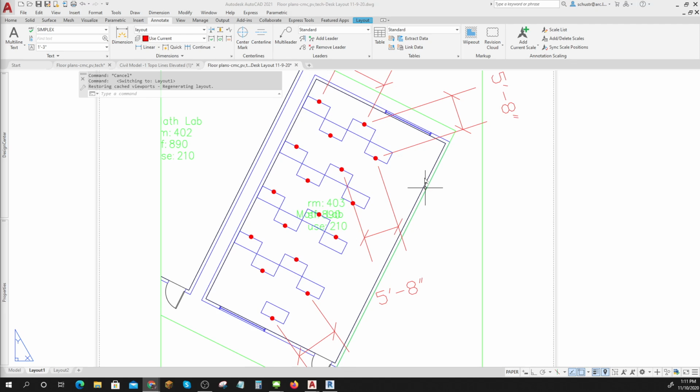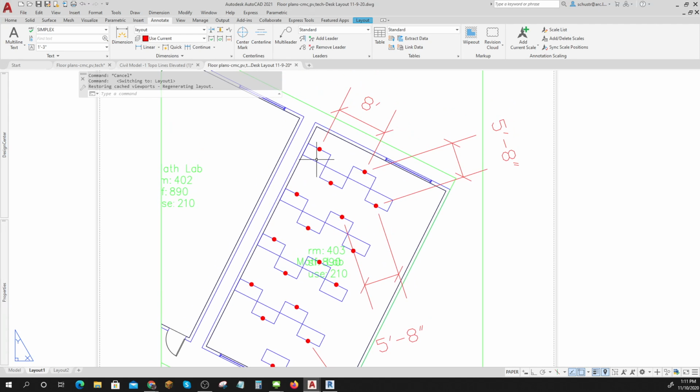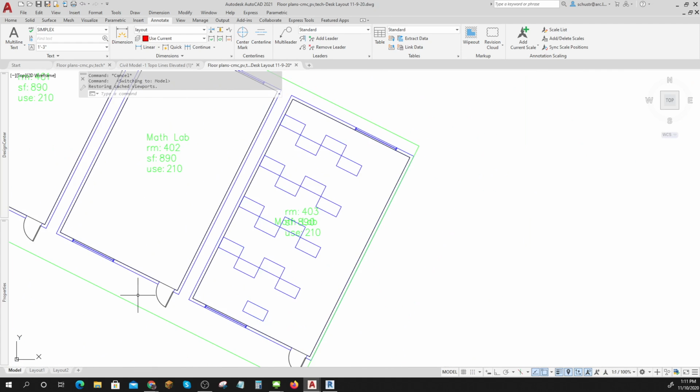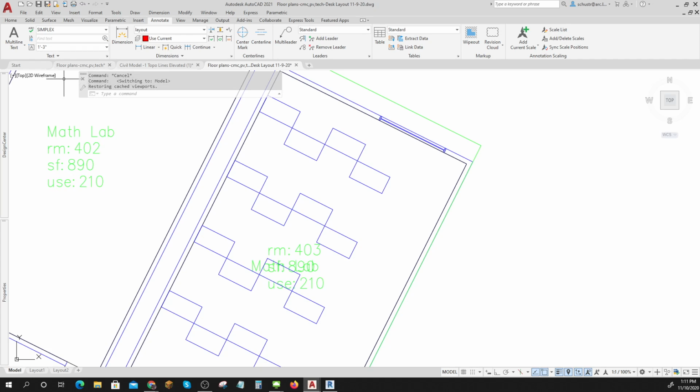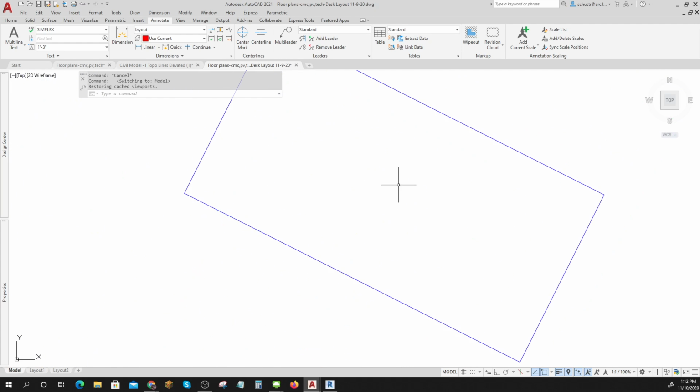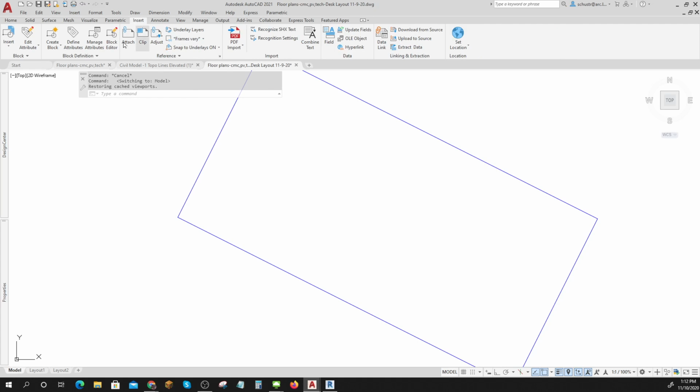All right. So, if I want to be able to find out stuff about these workstations and be able to transmit this and have it come out to the list of materials for our architects, I'm going to go ahead and in this model, I'm going to put what's called an attribute. And so I'm going to make an attributed block out of this. So there's my workstation. Now I'm going to zoom in, and remember, I could define an attribute.